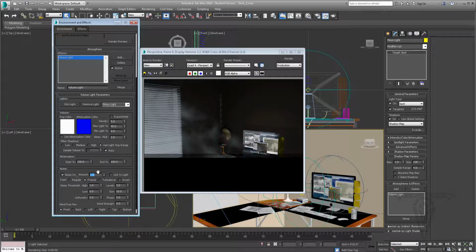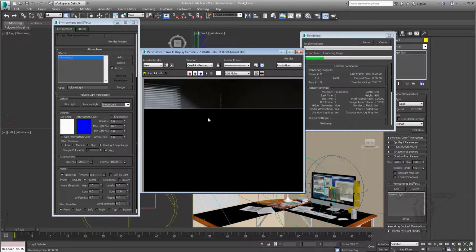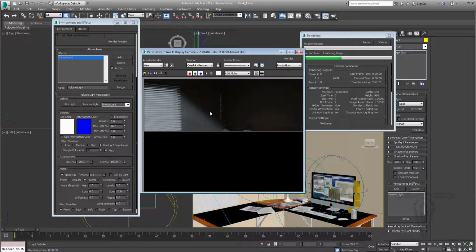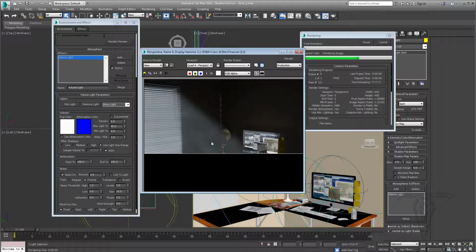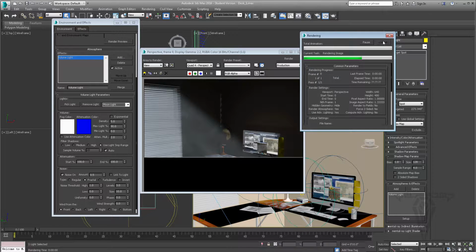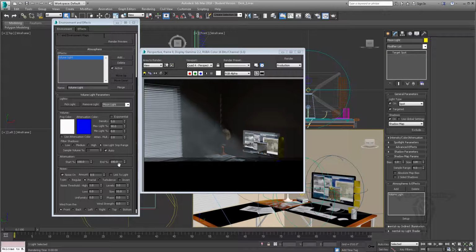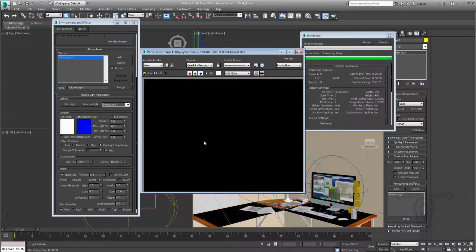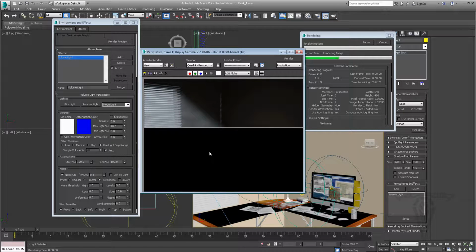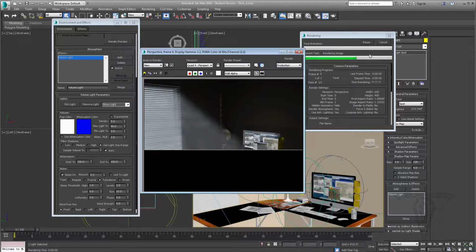And of course, the noise amount right here, let's say if I take this to 0.5, it's going to decrease how much noise is affecting the light. You can see it pulled it way down so it's not so extreme. And actually that's not too bad. Just to break up the light a little bit, as if there was dust or something moving through the scene. Let's go 0.3. Okay. And of course I can choose turbulence as well instead of fractal, depending on what kind of look I'm going for. I think fractal was definitely better.